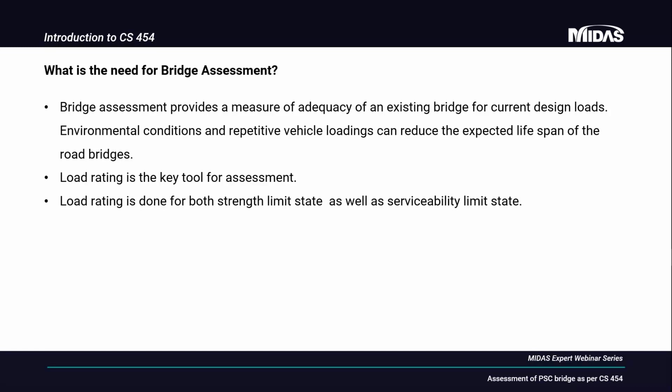Load ratings are expressed as a rating factor for a particular vehicle, and the emphasis in load rating is on the live load capacity and the approach to determine the rating factor, instead of the design approach of satisfying limit states. And load rating for bridges is done at both strength as well as service limit state. So with the understanding of bridge assessment, let's move on to CS 454.